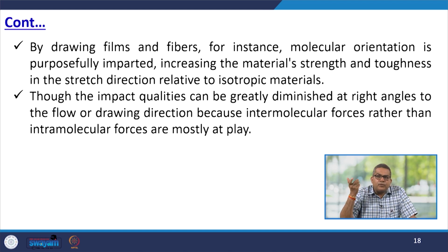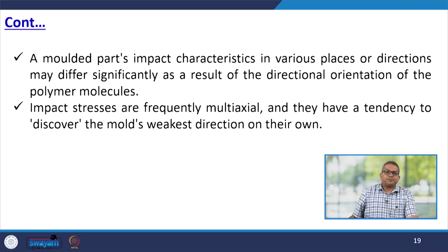Now, by drawing films and fibers, for instance, the molecular orientation is purposefully imparted, increasing the material's strength and toughness in the stretch direction relative to isotropic material. Though the impact qualities can be greatly diminished at right angles to the flow or drawing direction, because intermolecular forces are mostly at play.